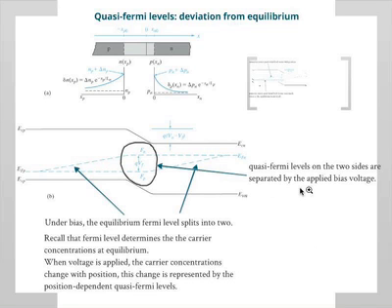So it should be pretty straightforward for you to calculate, for instance, where the quasi-Fermi levels are with respect to the bands, right? Because you know the equilibrium Fermi levels if you know the doping. You know the band bending, again from the doping under equilibrium. And if you know the applied voltage, you know how much the band bending has changed, and that's the difference between the two quasi-Fermi levels as well. So you should be able to draw something like that, given all the parameters.